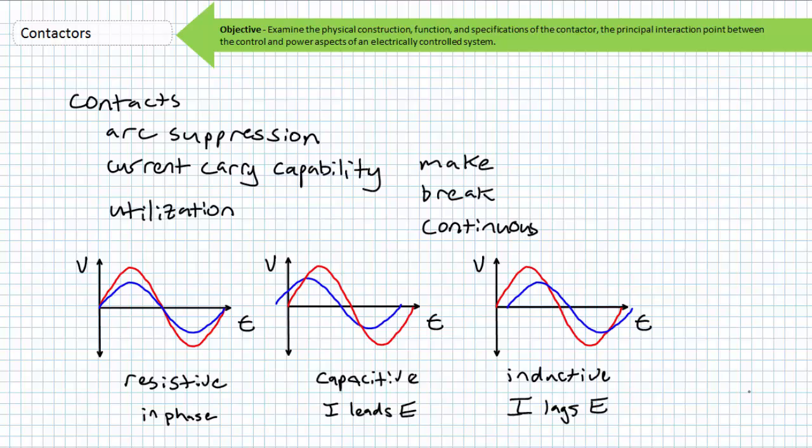AC voltage is characterized by repeated passage through a zero point between cyclical shifts in polarity. This means an AC arc extinguishes earlier than a DC arc, which does not have a zero crossing. Contactors rated for DC must be physically larger than AC contactors for the same level of current to account for this reality. High voltage and higher currents will require contactors with higher power ratings. Resistive, nonlinear, capacitive, or inductive loads present a different relationship of current to voltage. An inductive load, similar to the previously discussed coil, is characterized by the presence of a magnetic field. If the current is switched off, the collapsing magnetic field in the load can cause a great voltage spike if it is not properly suppressed.